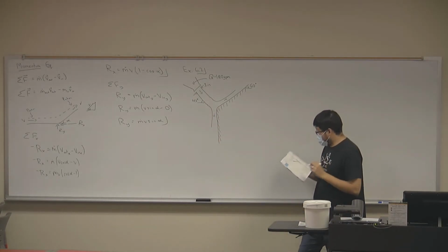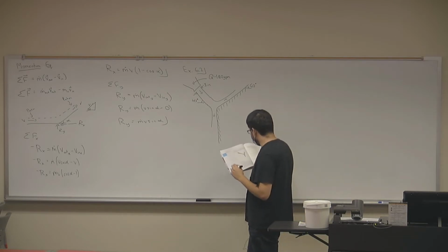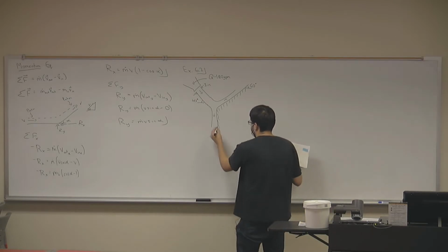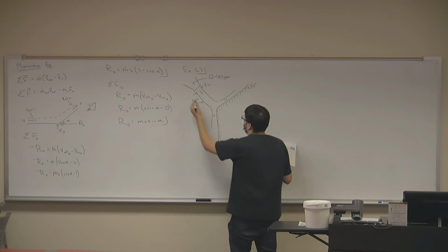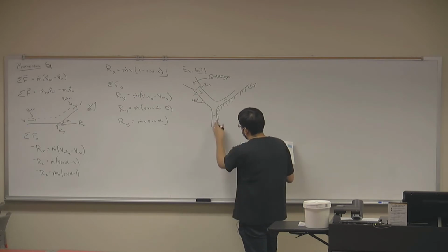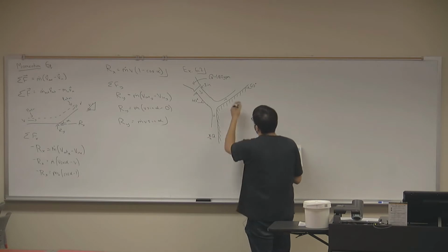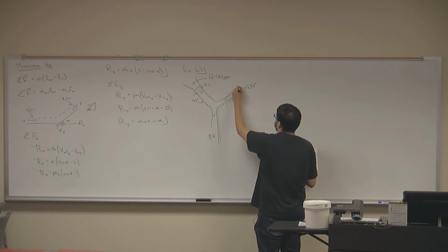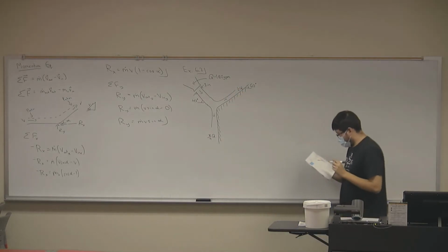Once the flow strikes the surface, 3/4 of the flow are going to move along this direction. So we can call this our inlet, we can call this our outlet, and this our outlet. So 3/4 of the flow are going to move in this direction, and then 1/4 of the flow is going to travel in the upwards direction.